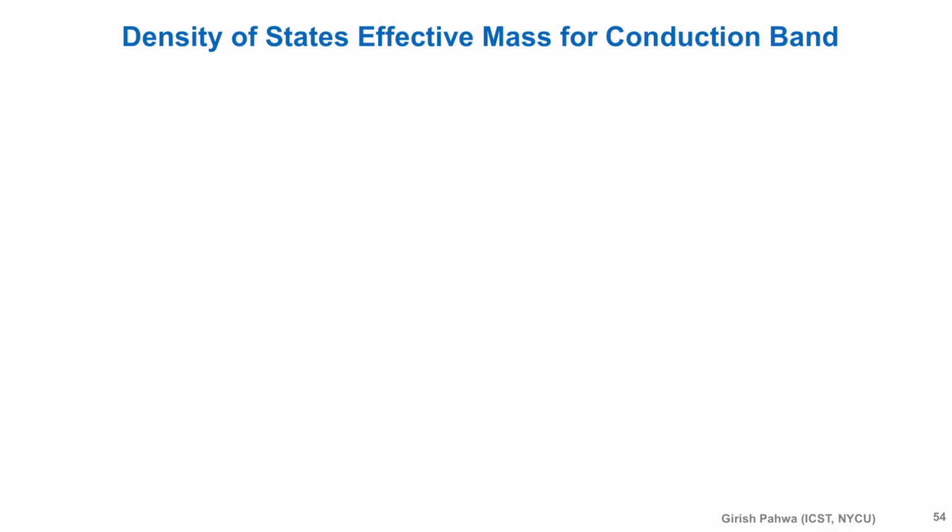how did we find that in case of silicon it will be an ellipsoid, not a sphere? Because we saw that the conduction band minimum was not at the center, it was along some special direction. In case of silicon, it is 100, right? Combinedly 100, I mean the set of all the equivalent 100 directions. There were 6 such directions. But in case of germanium, it is not along 100, it is along the 111 direction, all the equivalent 111 directions that you have.